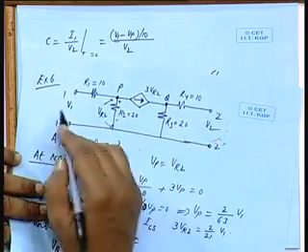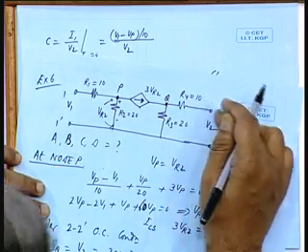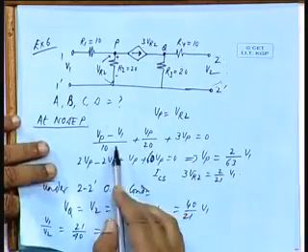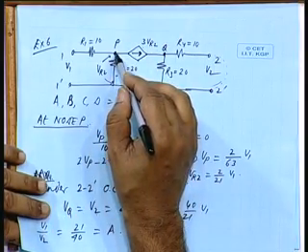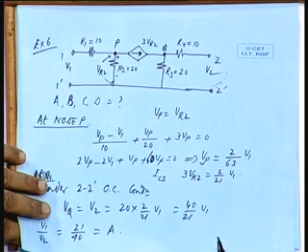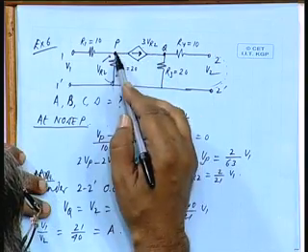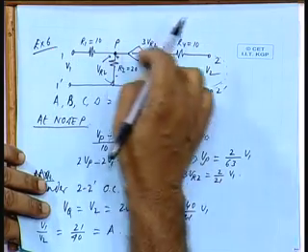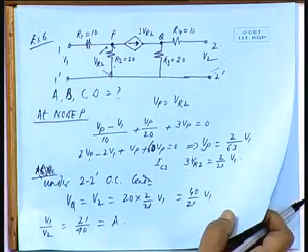So, I2 is negative and you are applying a voltage here. How much is that? Whether you short circuit or open circuit, this current supplied here is fixed. That is what we found here, is it not? For the node P, we got this equation from where this potential is fixed, and this current is dependent only on this potential, which is a fraction of the supply potential. So, this current is fixed; it is a voltage controlled current source.